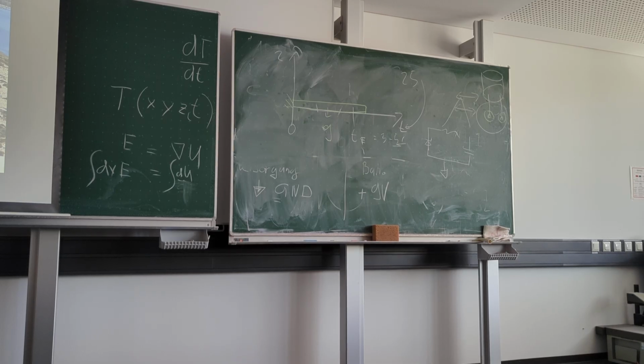Ctrl+Space, you can browse for various constants. Times, if you would have chosen absolute mass, then we should calculate, it's not so easy. What mass should we put here? We could not put the mass which a scale would show us if we put this bar on the scale. That's the reason why force per volume is very suitable here, Newton per cubic meter.